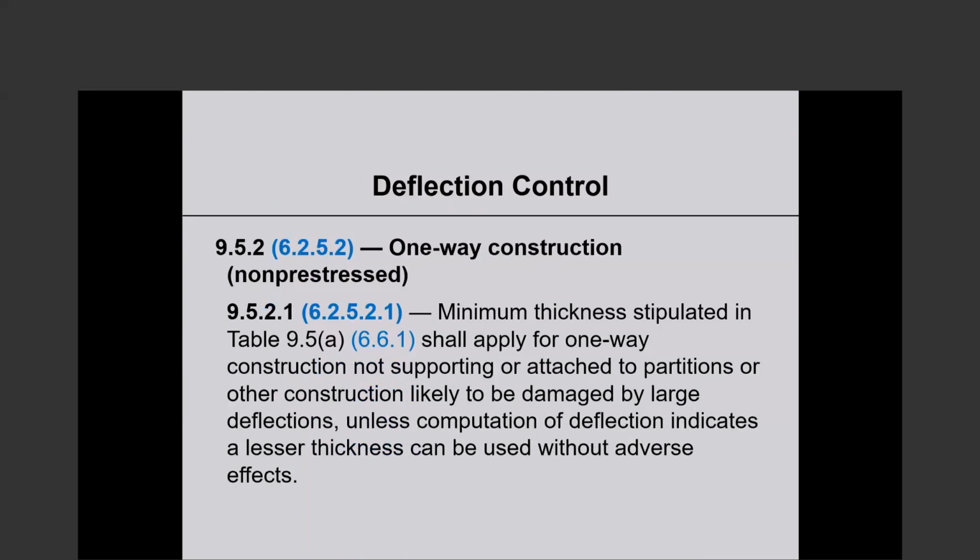I would like to go through this a little quicker because I'm not saying deflections are unimportant, but when it comes to calculation, we really do not have a handle on it even today. It's just a matter of fact. Calculated deflections are routinely different from actual deflections by 50% or more.